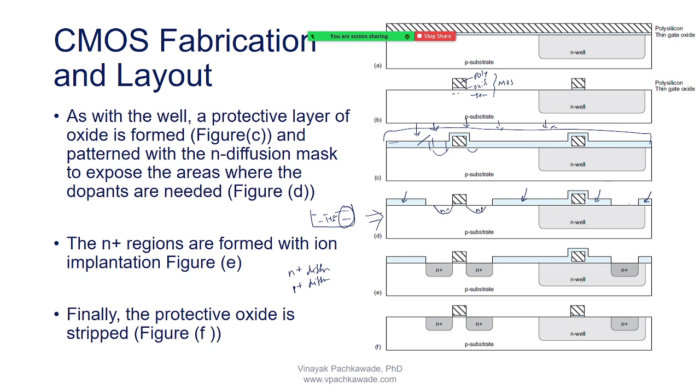Okay, here also it got etched. Why? Because you will have N plus here also, you see we want to have a contact of N plus, so this mask were put here, here and here. Okay, and then after etching the photoresist on top of this oxide was stripped away. So this is how we come at figure D.